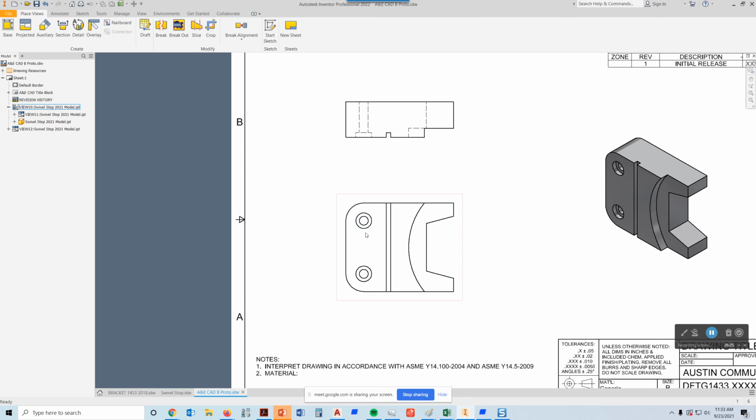But when you look at this view, of course, you're going to see those counterbore holes. You're going to see this big arc. You're going to see these angles. So all of that's going to go there because those are good profile views. And in the top view, you have this slot. Remember, we've got a 0.25 by 0.25, and you're actually seeing it in its profile view. So you're going to definitely put some dimensions in there.